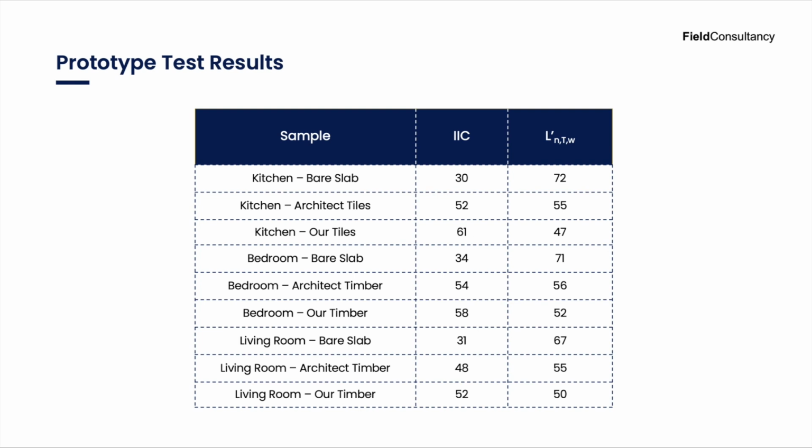As well as us coming up with our recommendations for the tiled and wood floor solution, we were representing the owner of the apartment below. So the architect that was appointed to do the renovation for the apartment above also had their version of their build-ups of the two different floor surfaces. So it became a friendly competition between the architect and ourselves as to what would come up with the best impact noise resistance to the apartment below. So remember, we specified that the design sound pressure level for impact noise was 55 dB.